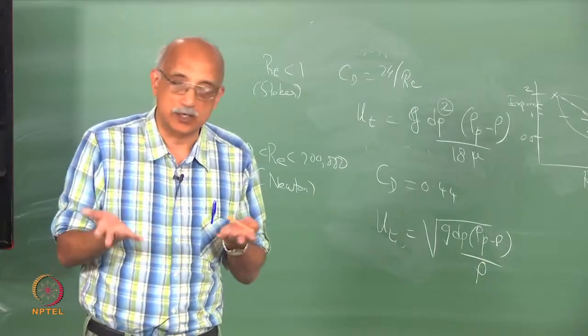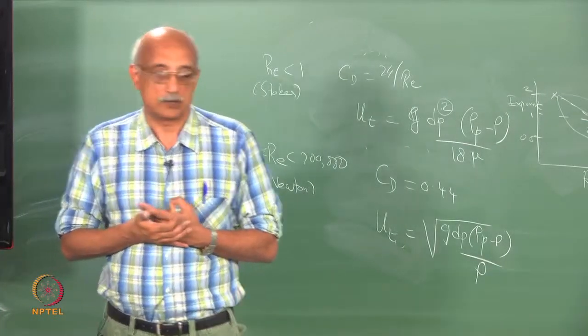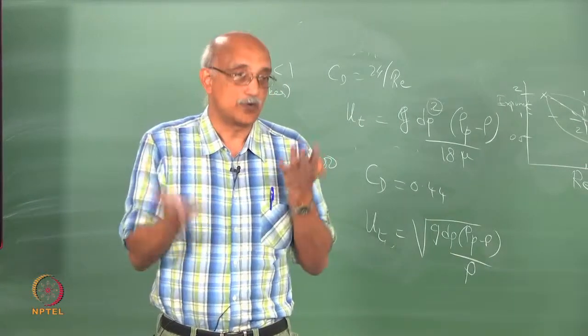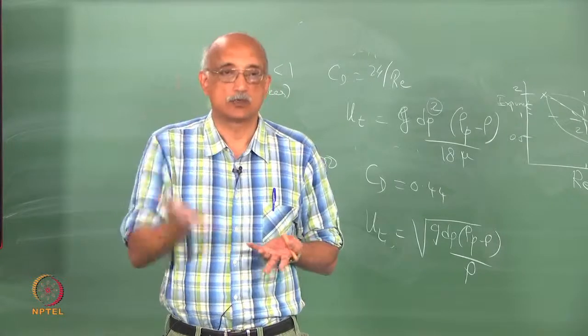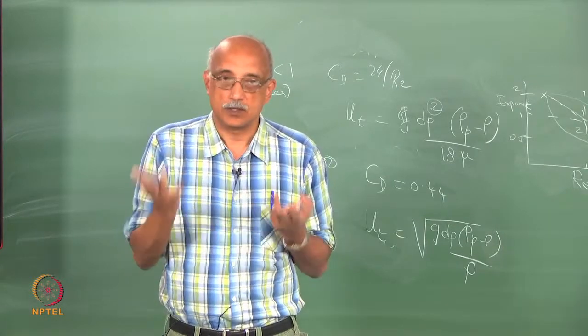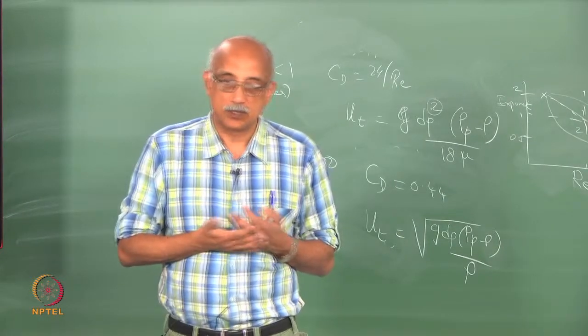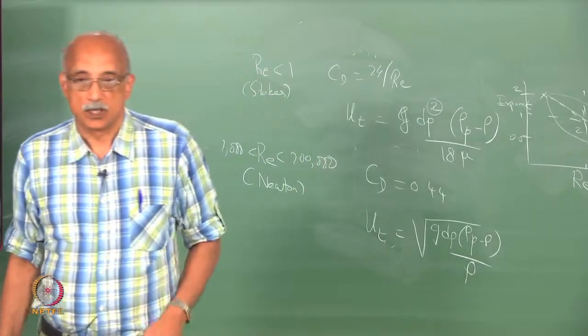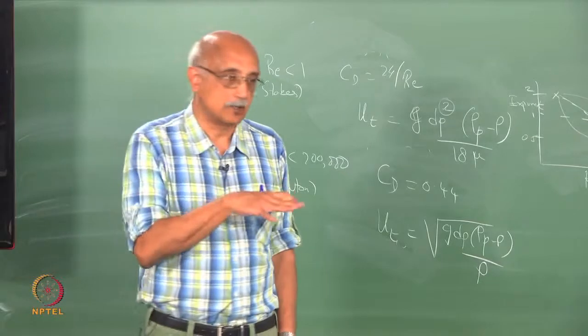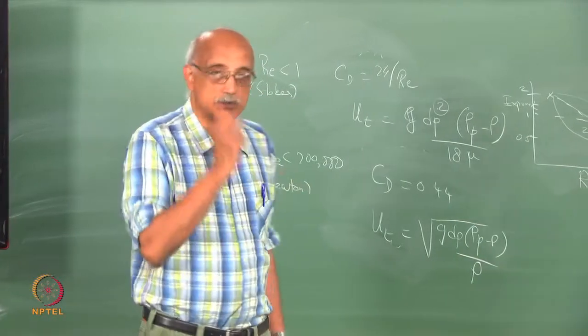Whether it's cleaning up of a contaminated fluid or whether it's causing a two-phase reaction between one set of reactants that are in the fluid and one set of reactants that are in the catalyst bed, an increased flow rate enables you to produce more output. And if you don't have to pay a delta P penalty, that's good.